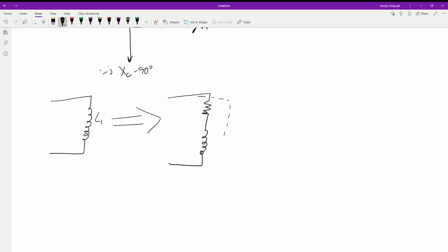And in here, this is inside the package of our inductor. So we're going to see a resistance of the winding, and then we're going to see the impedance or the reactance, inductance of that component. Now physically we can't split these out, but they are there. So just like before, you could take a capacitor and hook it up on ohms, and you should see an infinite, not an open, sorry, because there is no connectivity. There shouldn't be. If there is, it's not a capacitor. But with this guy, you should be able to hook it up to your ohm meter, and you can actually measure what the winding resistance of that inductor is. And if you don't account for that, it can throw you off.